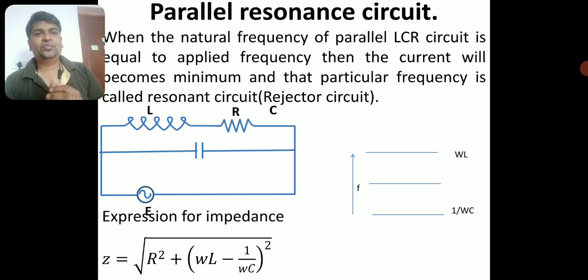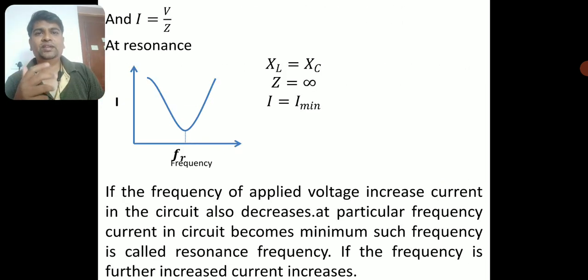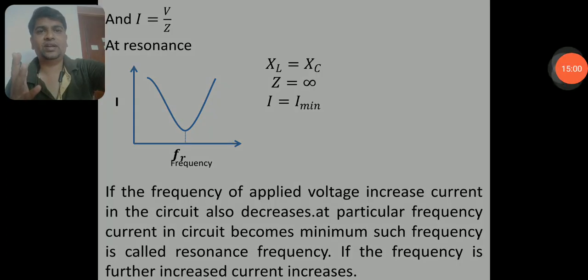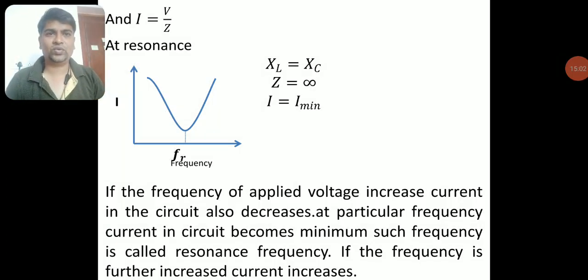Right. So we have a circuit like this. Inductor and the capacitor are connected in parallel, and this system is connected in series with an AC source. If I look for the resonance curve here, the curve will be exactly opposite to what I have seen in the series case. In the series case, it increases and then decreases, whereas in the parallel case, it decreases first and then increases. This is the nature of the curve I can expect in a parallel resonance circuit.